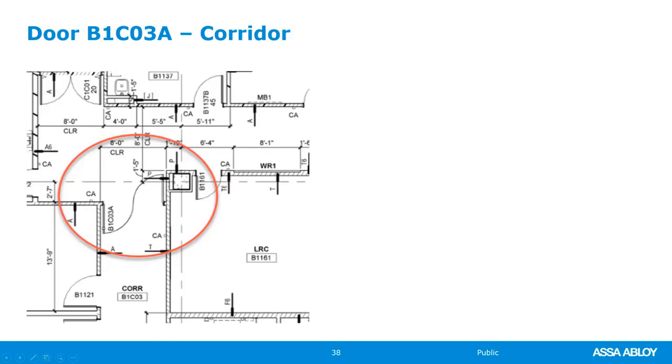And in most occupancies, you are not permitted to lock these doors. But this is a hospital, and I2 occupancies do allow controlled egress where the clinical needs of the patients require their detention or restraint. So card access on both sides, typically when you see that, that should raise a red flag. You're going to have to look up the special locking arrangement for your state.